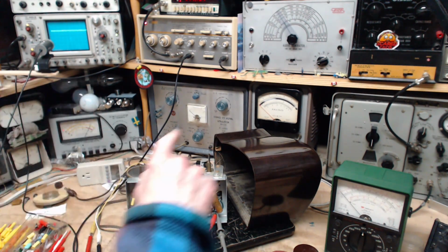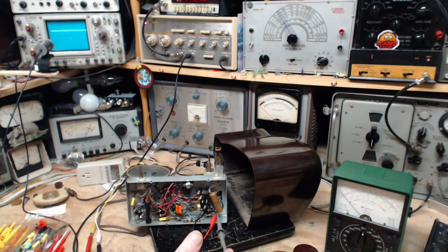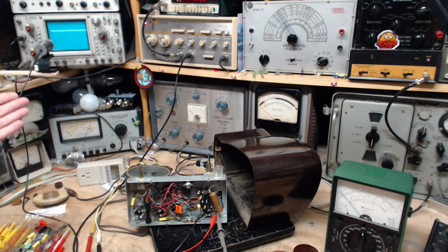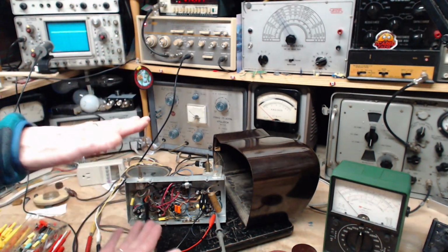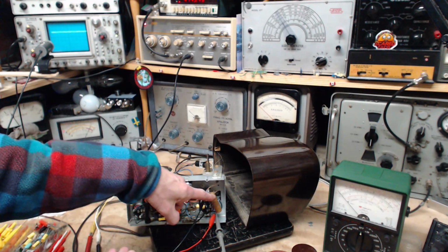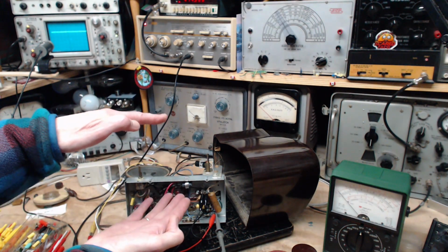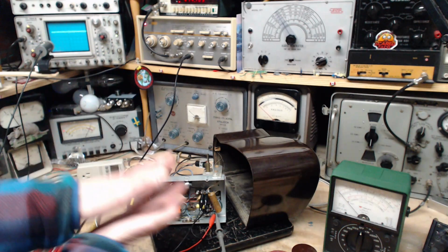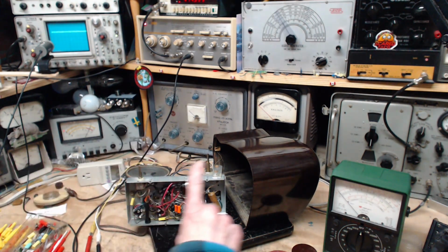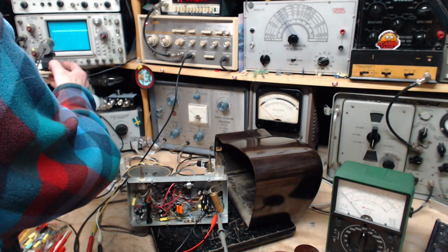So I'm looking for some kind of dip to mark where the resonance occurs. Outside of the resonance, this presents a fairly high impedance to the signal. So the signal from the sweep generator should remain high. When it reaches the resonant point, and this thing basically drops to zero impedance anyway, that'll cause the output of the signal generator to collapse. And it'll come back up on the other side when it crosses that critical frequency. That's what I think. Let's look and see.